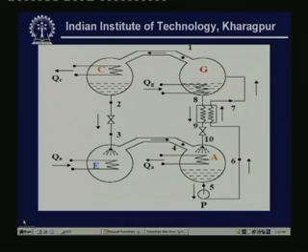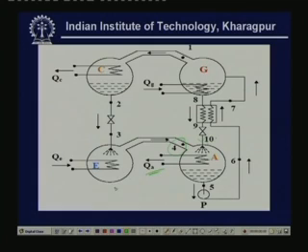And as you know, the working, low temperature low pressure vapor at 4 enters into the absorber, it comes in contact with strong solution coming from the generator at point 10. So, the solution absorbs this vapor and heat of absorption is taken out QA, and the resulting weak solution is pumped in this pump to the high pressure, and the high pressure weak solution flows through the solution heat exchanger, where it is preheated by taking heat from the hot solution coming from the generator. And this preheated solution, which is weak, that means which is strong in refrigerant, goes to the generator, where heat is supplied to the solution.